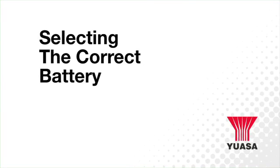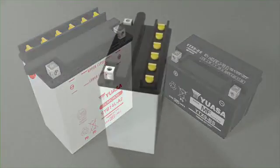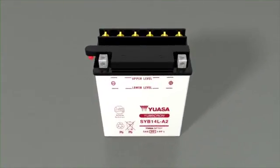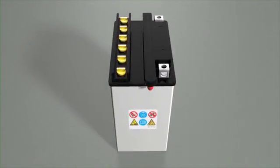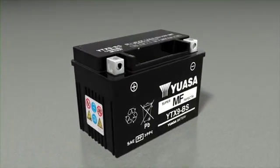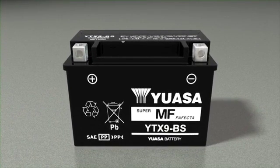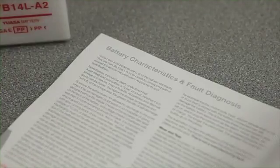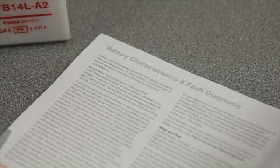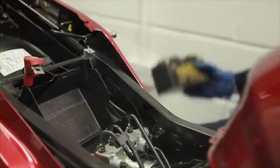There are many sizes, capacities and types of battery available. Yuasa manufacture 2 types of lead-acid batteries, conventional and sealed VRLA. Externally, both types of battery appear similar, but a conventional battery has filler caps and a vent hose, while the sealed battery has a removable sealing strip and a safety valve which is molded into the outer case. But internally, they're significantly different. The Yuasa technical manual contains more information on the internal makeup of each type of battery.